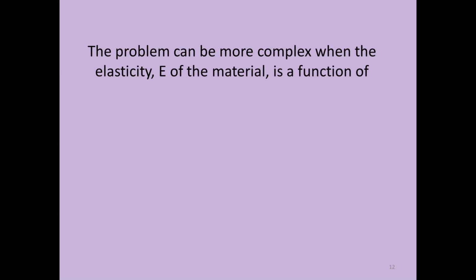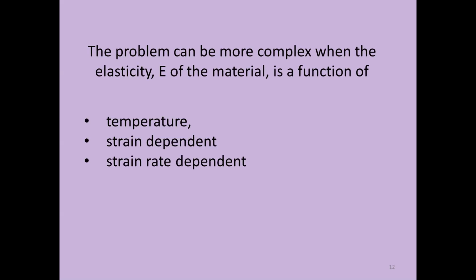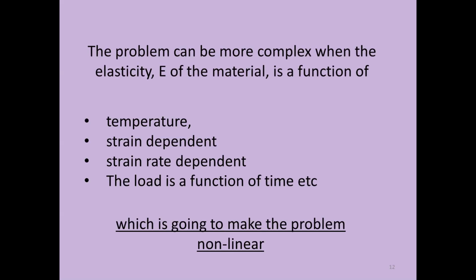The problem can be more complex when the elasticity of the material is a function of temperature, it is strain dependent, it is strain rate dependent, and the load is a function of time and some other factors also. All these factors and many more of them are going to make the problem nonlinear in nature.